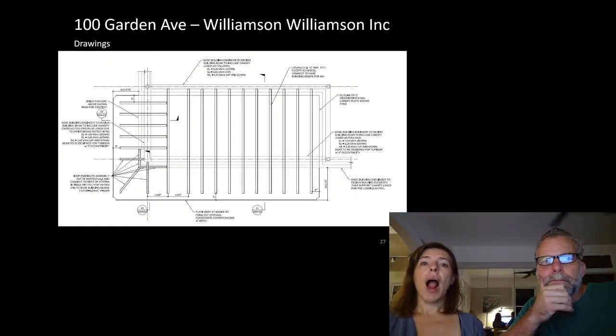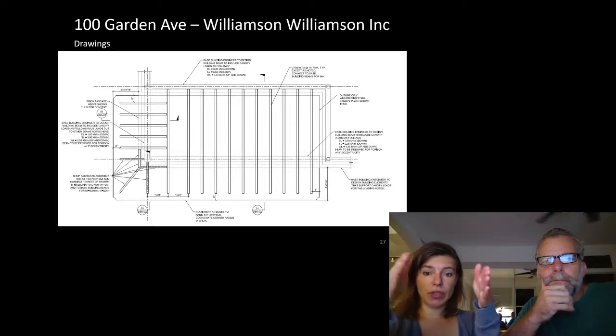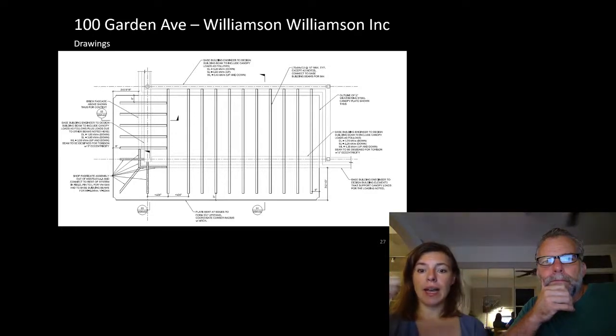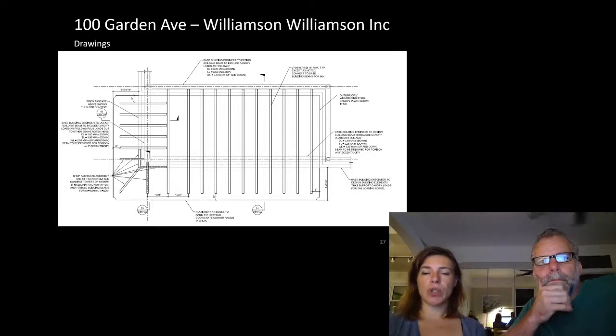So what this is basically a steel plate canopy with upturns on the edges and the corners cut out to be the gutters. This is tilted to drain to where they need it to be, but that meant none of our structural members could go all the way to the edges. We needed to allow water to run in between the members and then down to those gutters.